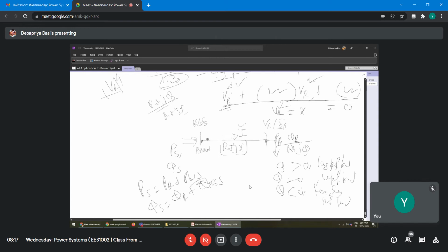So direction of the power flow is from sending end to receiving end, and here if you get 14.8 megawatt, then loss will be 0.2 megawatt, right? Whatever you measure here, whatever you measure here, this is for real power. Whatever you measure here, it will be different, right? Because loss is there along the line.